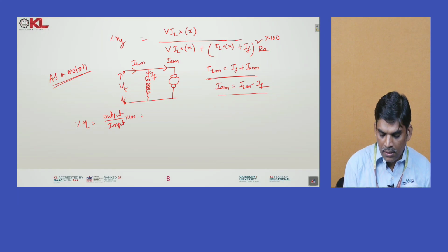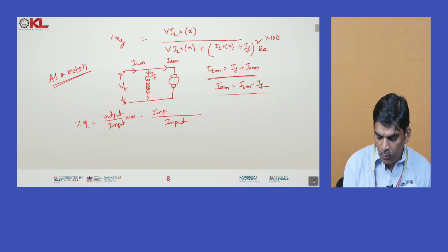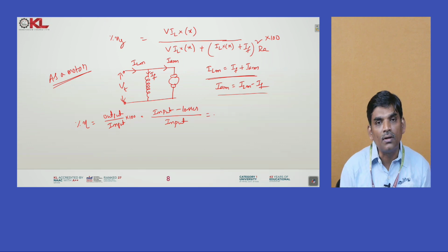In the experiment we are providing some electrical power, and the nameplate details give the electrical power formula. We can consider it in terms of input, so we note down this efficiency formula: output is equal to input minus total losses of the machine. Input minus total loss of the machine.